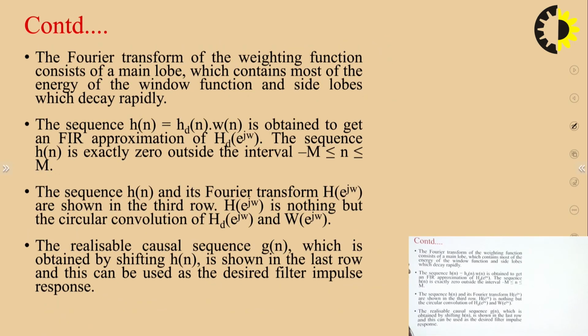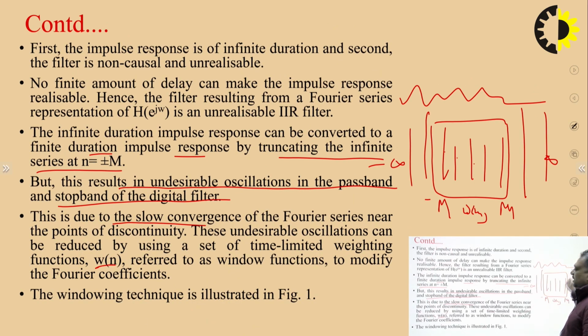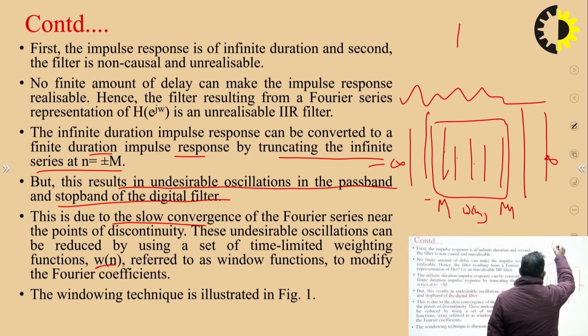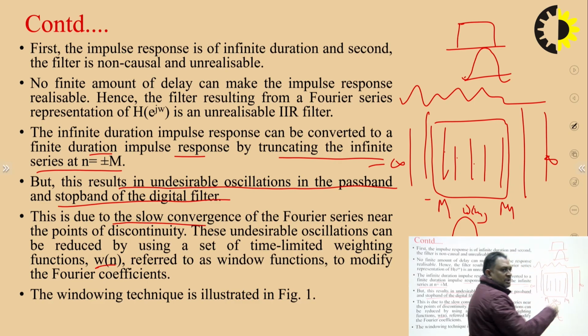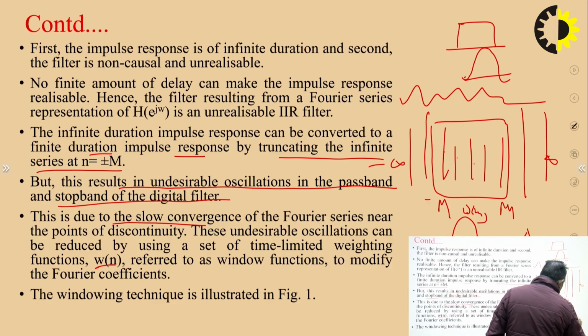So what we want to say simply is, if we choose a rectangular type of window, we get Gibbs phenomenon due to abrupt truncation. But if we choose another type of window, like this is your initial rectangular window, after that let us say we have the Hanning window, whose shape is like this, then the Hamming window, which also looks somewhat like this, but these are mathematical functions. If you see the mathematical function, then you can find the difference. And the last window is the triangular window.